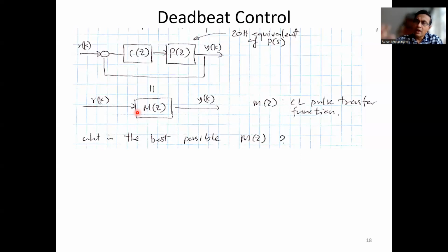So let's say I have an ideal controller, right? Which means when I ask something, it gives it back to me. Let's say a temperature control system, let's say an air conditioner. I just ask, I want 25. And in a while, it gives me 25. And then I ask 24. In a short while, it gives me back 24. So that is the ideal controller. Okay. This is what everybody is after, right? When they design control systems.